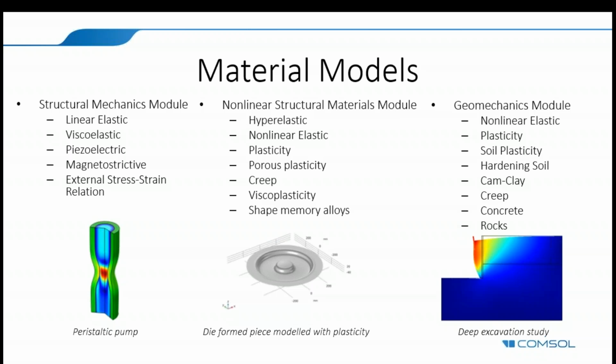So for example, if you have a metal powder which is in a die that is being compacted through a pressure applied by a punching tool, while this process is being simulated, and the porosity of the powder is decreasing, the density and the strength of the material is increasing, you can actually track the porosity during this process. These types of material models are important because they allow you to accurately compute the final porosity of the material once this compaction process has been completed.